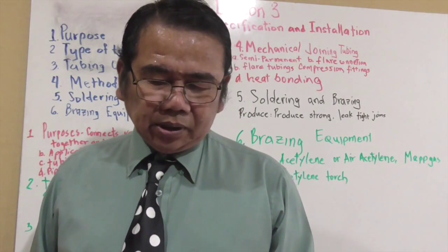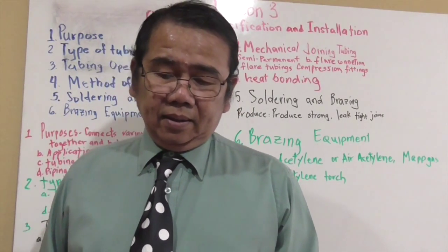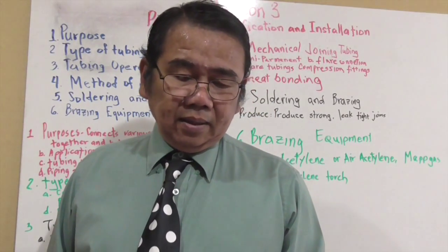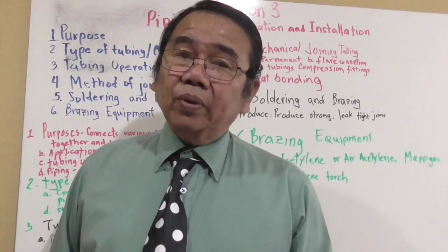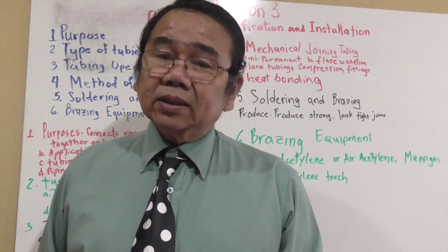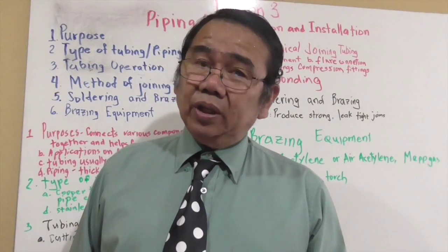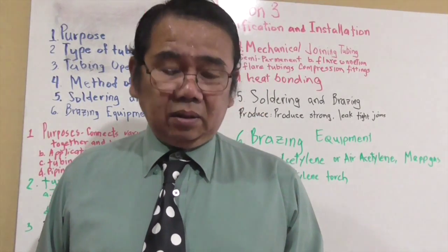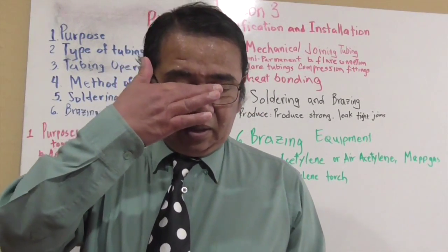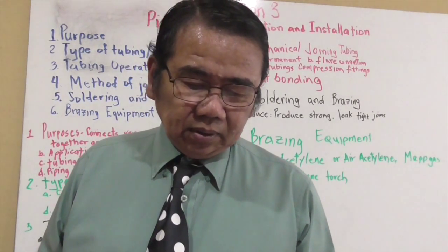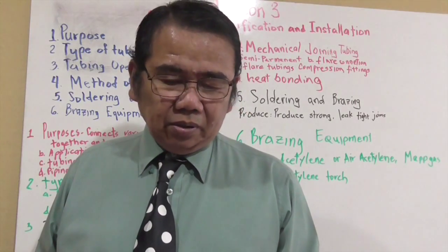Silver solder is safe to use when joining copper tubing and fittings. When done correctly, silver solder will be stronger than the metal it is joining together. There are several types of silver soldering.